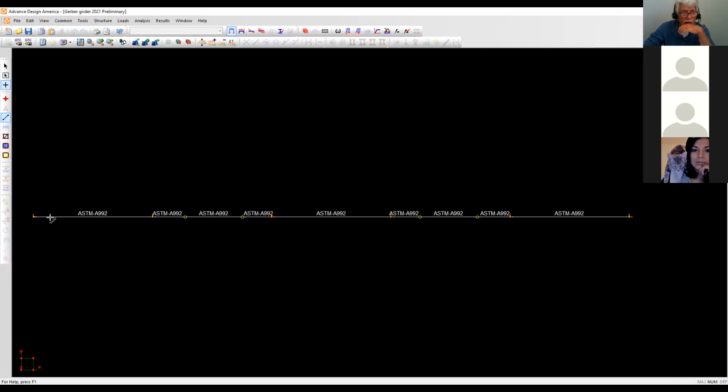Be very consistent. Always go from left to right, left to right, left to right. This way you know that you're moving from the beginning of the member to the end, and this way when you look at the results on the table, you know at which side is there, and what's happening at the other end. So you add your members. Once your members are added,